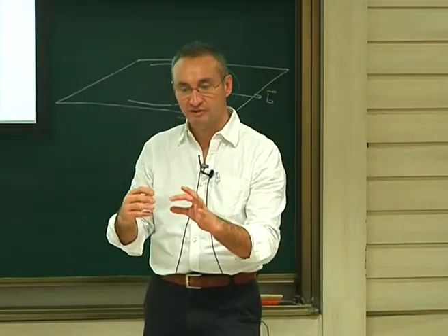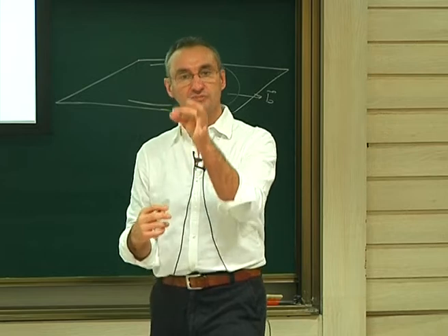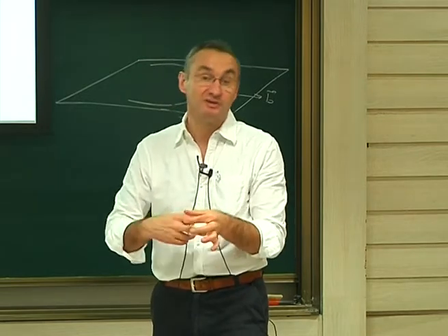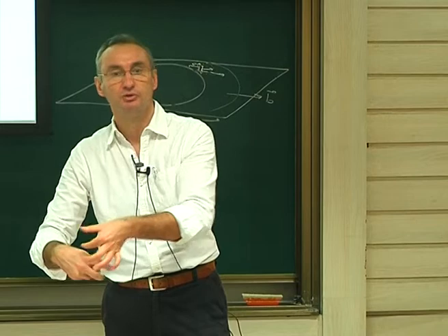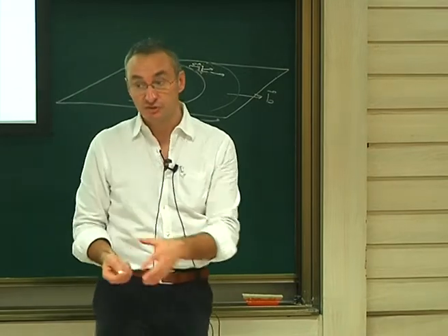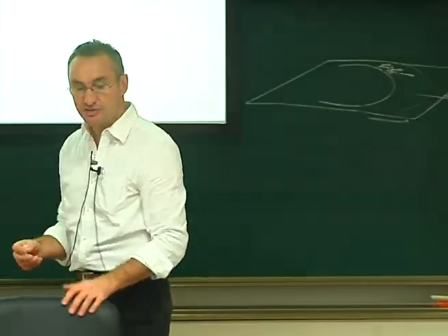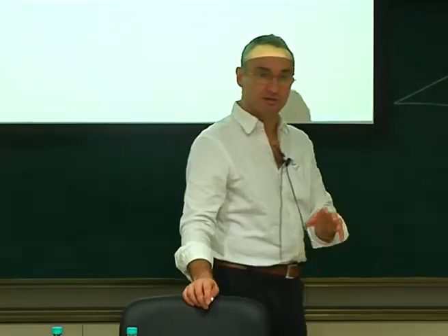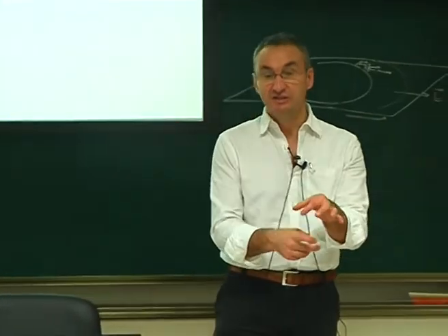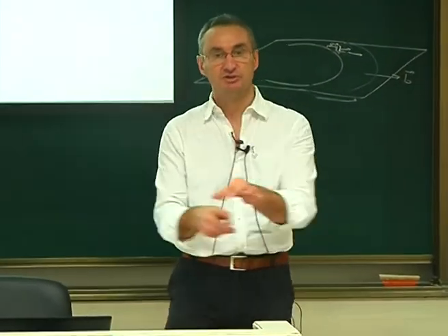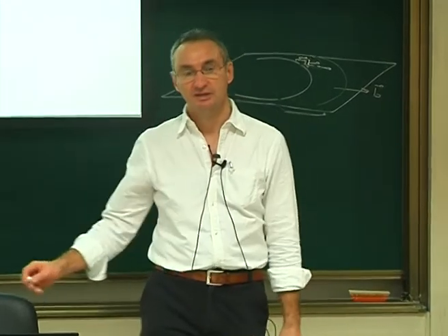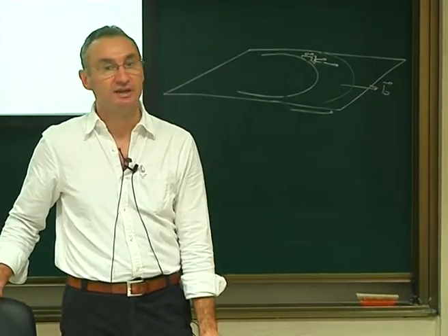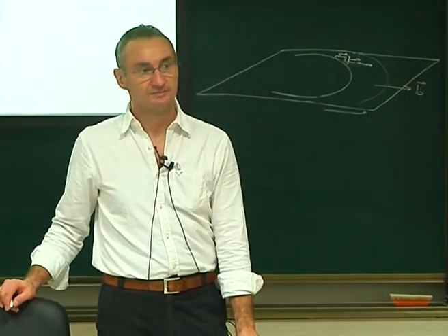Every time dislocations move, they move the loop only a little bit, because they are going too fast, actually. So since they go too fast, the loop cannot follow. And this is very, very famous. There is a nice study from Bacon on that also, David Bacon in England, who explained that indeed there is a velocity effect of this dislocation-loop interaction. I did not know this before, but indeed it has been demonstrated in molecular dynamics simulations. Okay.